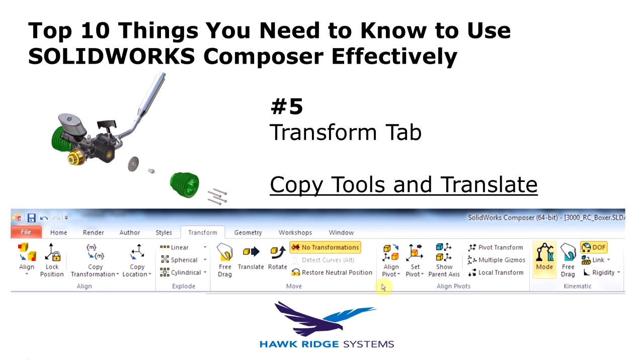Number 5. So we're halfway through this. The Transform tab. So there are tabs at the top of the Composer interface here, and the Author tab and Transform tab are the two main things that you really need to learn in order to be effective with Composer. Between the Transform and the Author, the Transform tab is number 1 on my list. What we need to really pay attention to here are the copy tools, which are the copy transformation and the copy location, and also the translate tools, which are here, basically translate and rotate. Free drag, try to avoid that, it just causes problems.